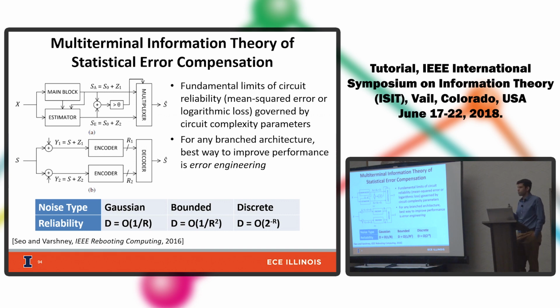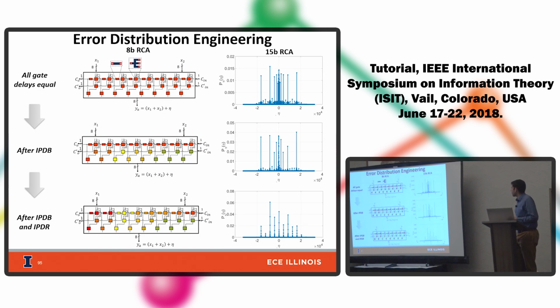Right? And so you want to really move in this direction if you can. You want to engineer the noise so it's more and more discrete. And that's the high-level design principle that emerges from this analogy, that we want to engineer the noise, which we can because it's a circuit we're designing, to be more and more discrete if we can. And that's what will give us the biggest gains. And in fact, Naresh and his student Ameya have been able to do this. So they've been able to take noise that was basically a continuous noise and engineer it such that it's very much discrete. And this, by the insight from the rate distortion theory, tells us will perform much better than it would otherwise. So you get the pithy insight: engineer your noise so it's discrete from the information theoretic principles, and then you can go ahead and actually do this with circuit design techniques.